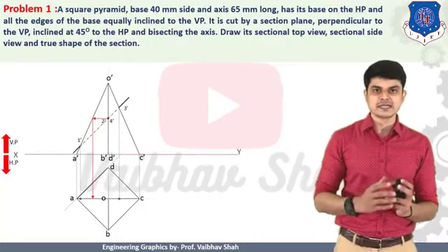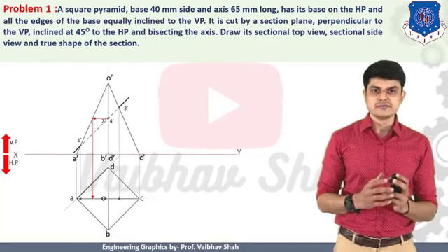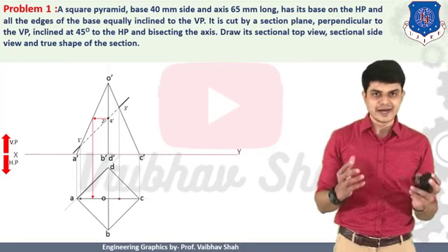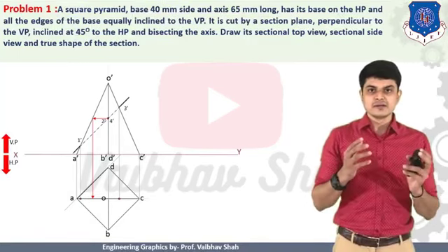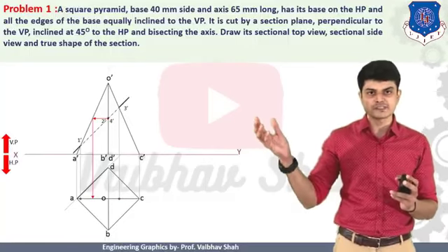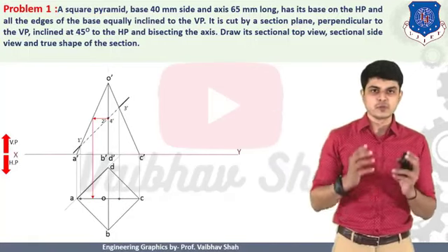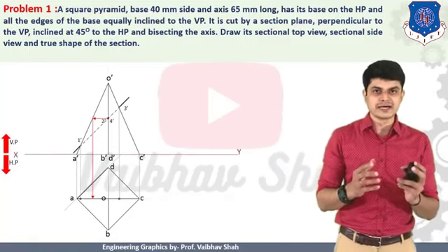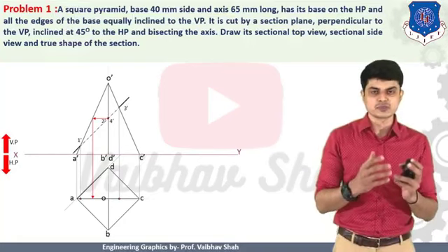But let us ask ourselves, does this point belong to the OA line? Yes or no? No, right? This point only belongs to your OB and OD lines, but since it was not possible to transfer this point, you have transferred this point for simplicity onto your OA line, and thereafter we have plotted this point. So what to do? Don't worry. Now we should give the point back to the lines it belongs to.